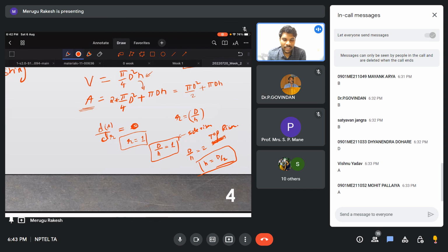So you are asking, for large castings, if the diameter is big, is it advisable to keep the height of the riser that much? In that case, you can use a top riser, in which the height is half the diameter.